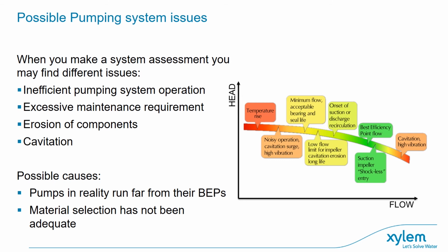The mechanical losses are due to the friction with the coupling and the mechanical parts, while the hydraulic ones are all the obstacles that are met by the fluid during its path. Basically, we're talking about flow friction, recirculation, as it was named before, and actually also internal leakages and backflows.